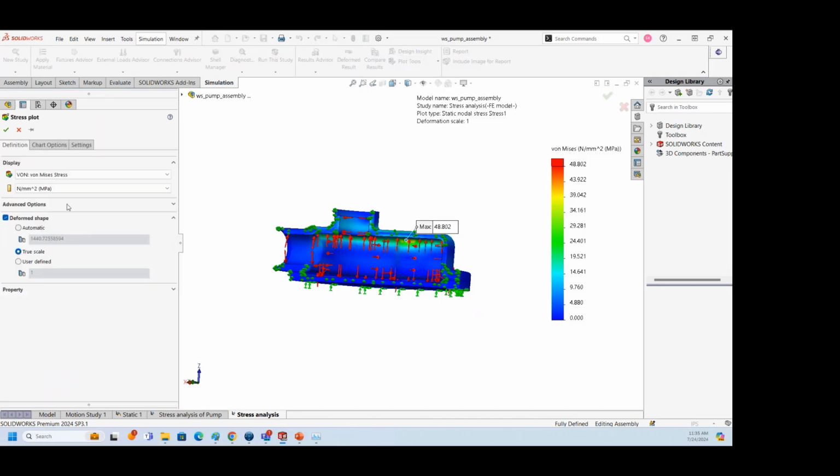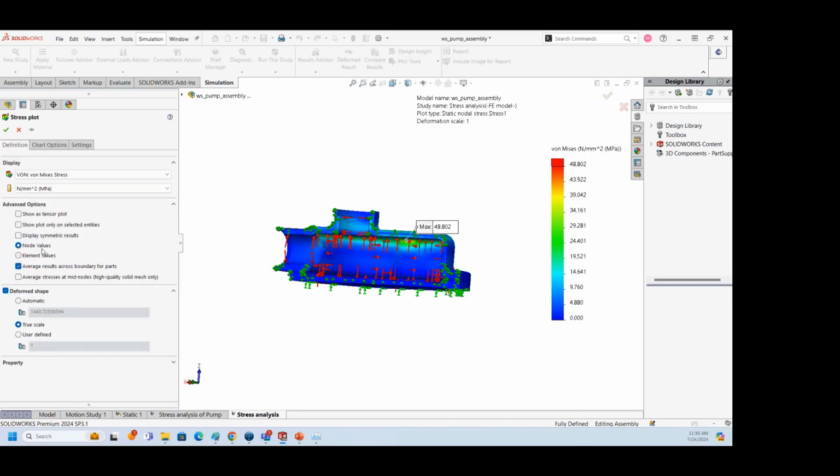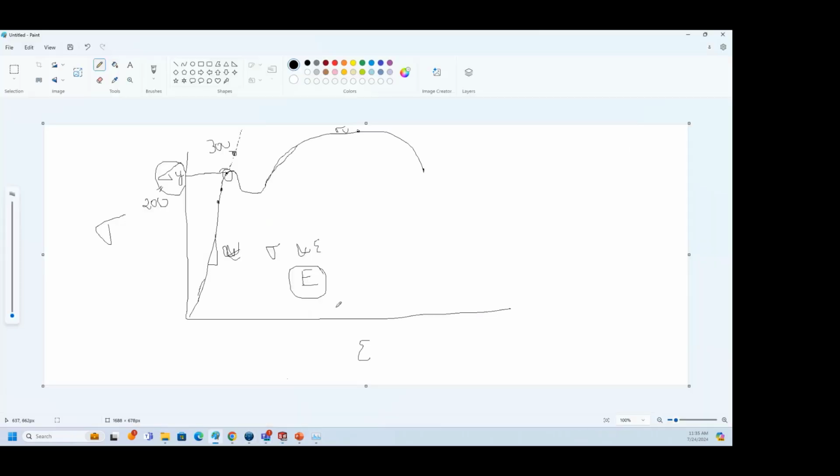And one more thing you can see is with respect to the nodal and elemental value. Basically, if I just consider this as my model and I have meshed with four elements, 1, 2, 3, and 4, right, and these are my nodes. The results are going to be calculated at a different location, which is called the Gauss point. So these results are interpreted and come to each node. This is how the back end of the FEA works.